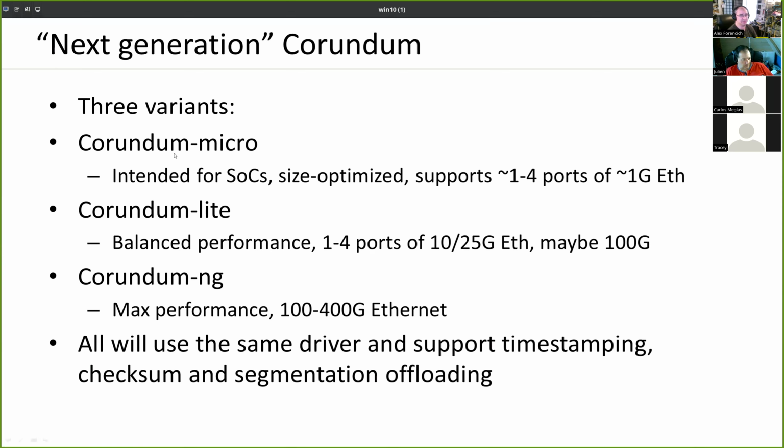And the idea is to be able to use the same driver and have a very similar software hardware interface for all these designs, right? The same kind of descriptor queues for packet transmission, and some kind of queues for control, things of that nature, just to keep things as consistent as possible. And then the plan is that all the designs will support the basic offloading and timestamping. So checksumming, segmentation, and timestamping.